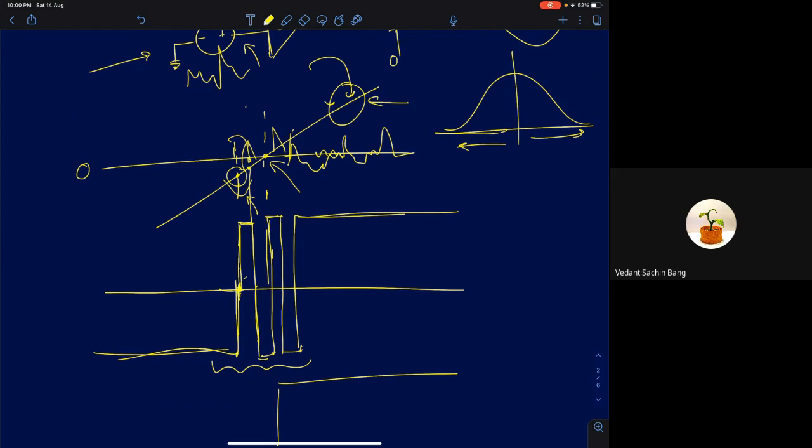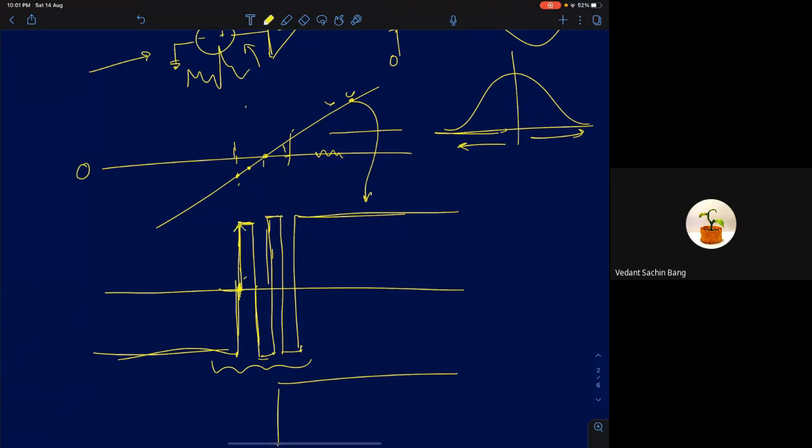Is that fine? So even though there is noise, I've drawn a clean waveform here. That's because the signal voltage level is much higher than the noise level. So we are fine. The problem happens at the decision making process. At this edge, the problem occurs. This phenomenon is called false triggering. Most digital systems operate on edges, rising edges or falling edges. Now you end up giving unwanted edges to the digital system, and it might even fail.